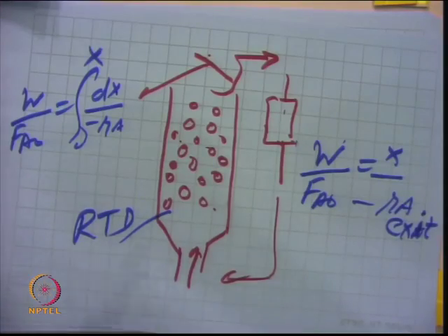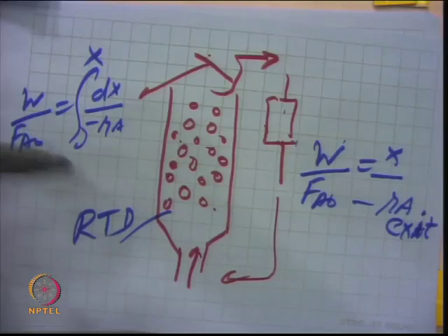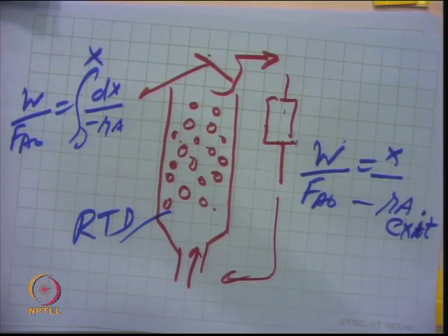So, RA, the rate of reaction, is not again just a kinetic control, it can be a function of hydrodynamics, that is the velocity term, right. So, accordingly your mass transfer will be there. So, there is a bubble phase, a solid phase, a wake phase, and there will be a transport. So, accordingly there will be additional resistances which may come, and the rate may be slowed down, right. So, that is another issue in the case of fluid bed reactor.